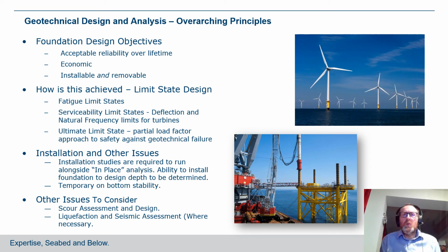So just to go on to talk about geotechnical design and analysis now, and to start with some overarching principles. The objectives of foundation design are to provide an acceptable and reliable solution for the foundations over the lifetime of the structure, for the foundation solution to be economic and also to be installable. We do this by looking at a number of things. First of all, we undertake limit state design and look at various load combinations on the structure.